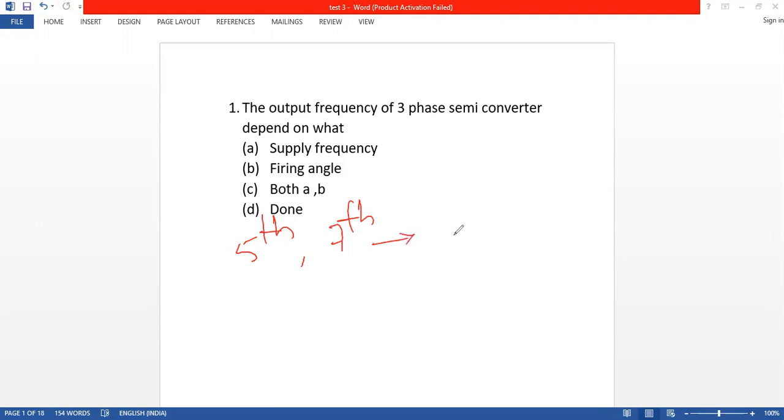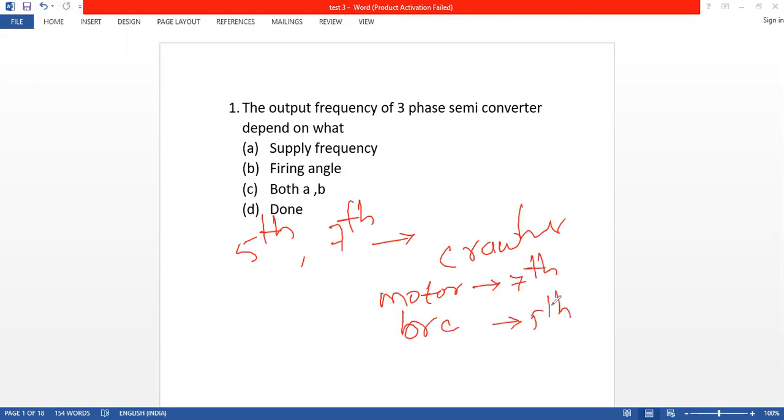So you have crawling in synchronous machines. If it is motoring mode, remember it is due to the seventh harmonic. If it is braking mode, it is the fifth harmonic. So what will you do to eliminate crawling? Short pitch winding, short pitch winding with skewing.